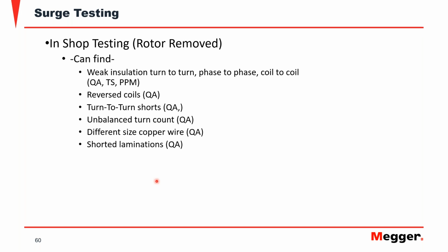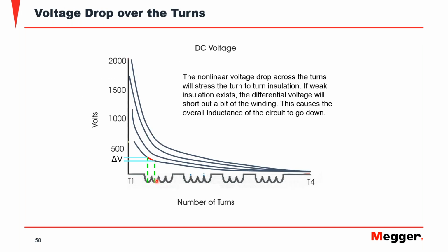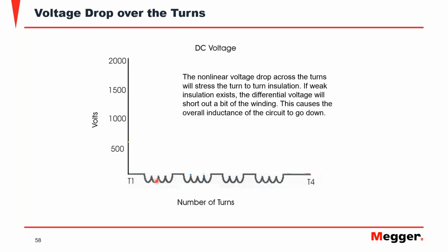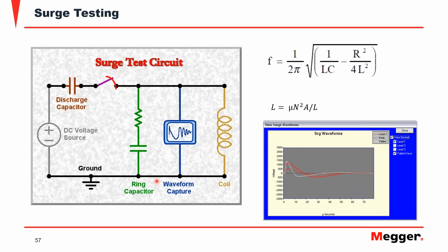Now remember that the inductance can be affected by mu. It can be affected by the number of turns, by the area of the coil, and by the length of the coil. Any of these parameters that changes will matter. Here we have the permeability of vacuum represented in this equation, but a typical equation with magnetic material will have the permeability of the magnetic material multiplied here.